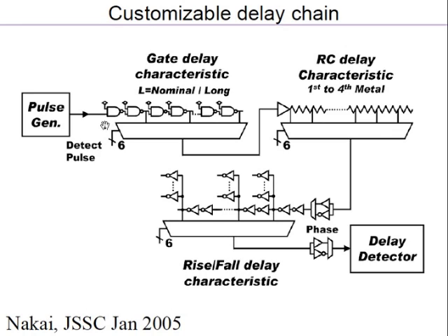And then what you do is you measure the delay out here. Now this whole thing you can configure as a ring oscillator. You can take it and put it back. As long as there is an inversion, it will keep on oscillating, and you measure the period or a frequency. That is one way of making the measurement. Now when you say measure the period or frequency, you want to do it in the chip, not put it in a scope and see. It has to be all built in inside, automated, right? How do you do the period measurement? So it can be a little tricky, whereas delay measurement is relatively simpler. So that's what they do.